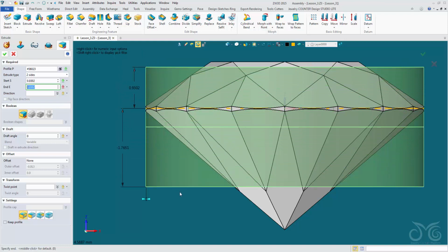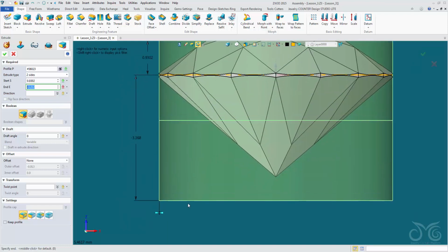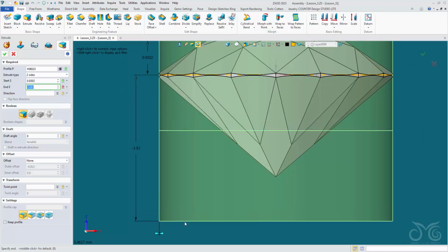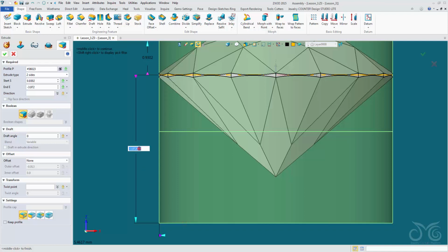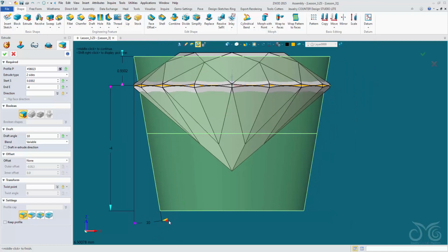And then we will take the extruded shape, this bezel. It's around here. Let's say 4. Let's enter in -4 here. Enter. Okay, now I'm going to add a draft onto my extruded shape. Let's use my direct editing here. It's a lot more visual. We can drag and see what we like. In fact, I did like the 10. So we have a 10-degree angle here.